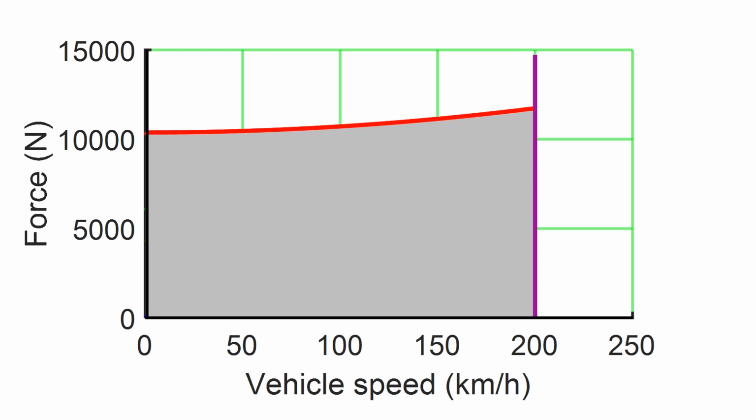And if the customer also doesn't see this performance requirement as a must-have, it might indeed be possible to reduce that requirement. The cost of the powertrain depends on several factors, and the required wheel force is one of them. The higher the force required, the more expensive the drive shafts and the gearbox become.